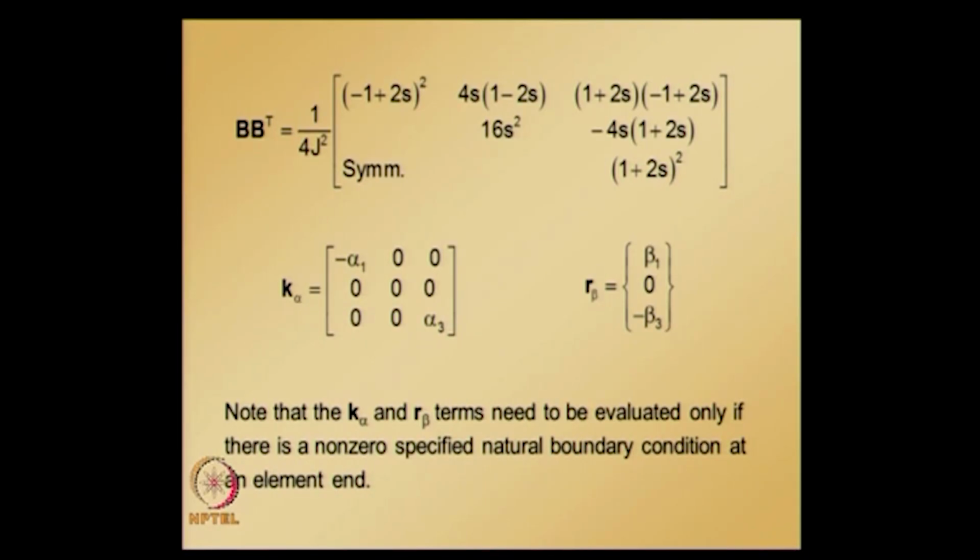So we will solve the same problem now using quadratic elements. If you recall, when we discretized the domain using 4 linear elements, the critical buckling load that we obtained for the column buckling problem had about 5% error. Now let us see how much improvement we get using this quadratic element for the same number of nodes for the entire domain.